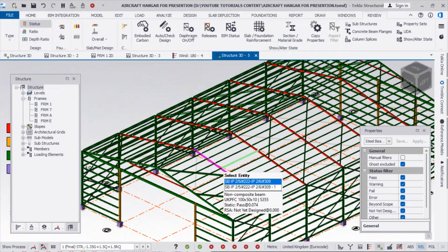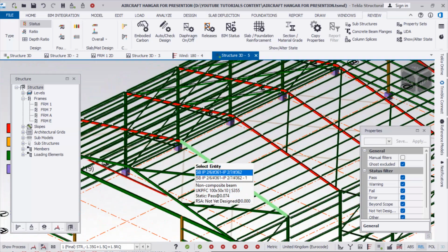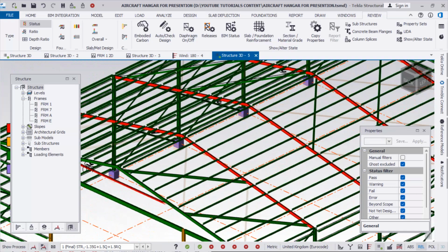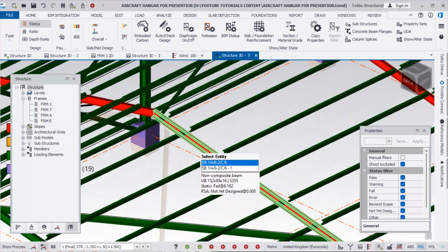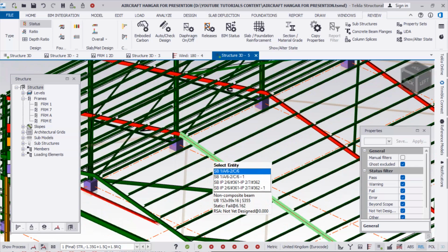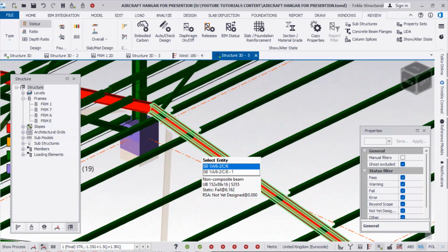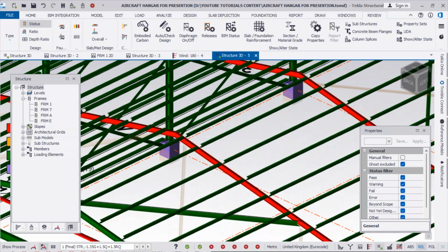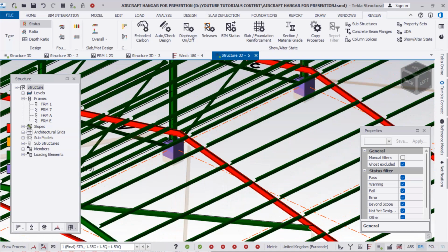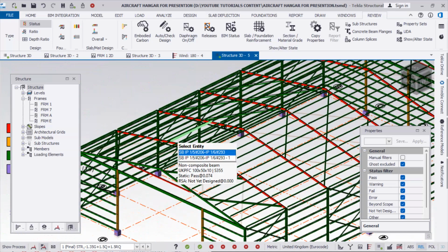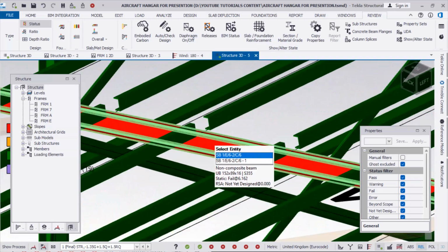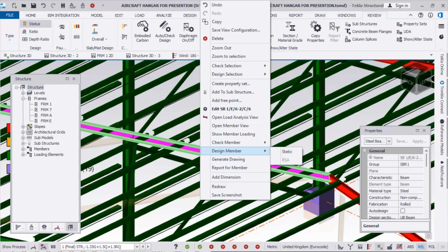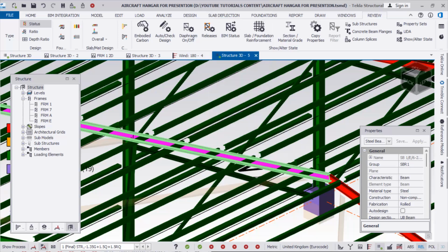And if your beam is failing by deflection, of course, what that means is that you should increase the depth of that beam so that you make it stiff along its depth, and in that case it's going to be able to withstand deflection. So let's just design one and we see the section size that is demanded. So just click this one, right click, then go to design member and go to design static.